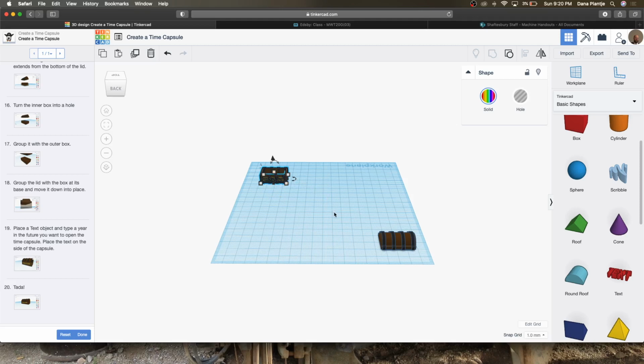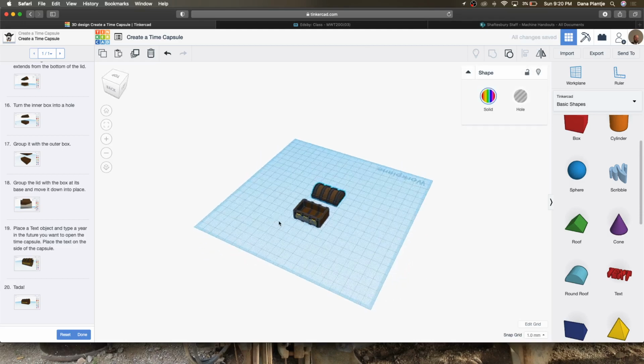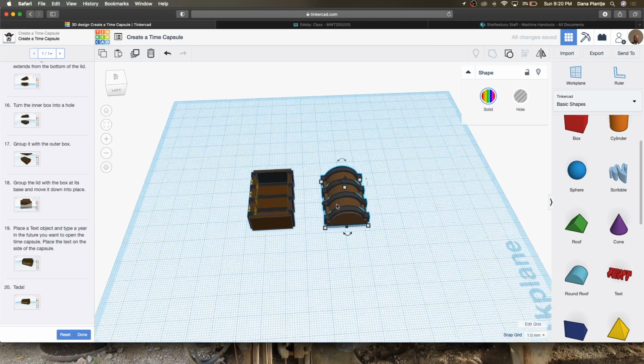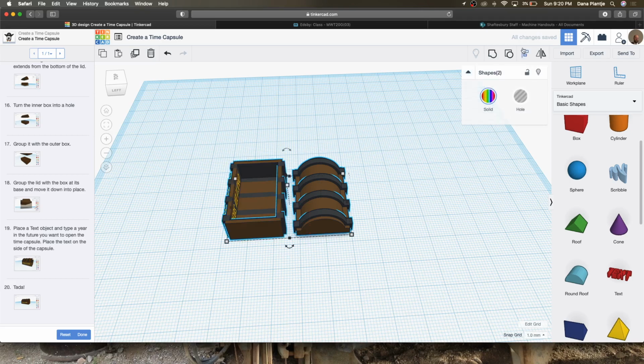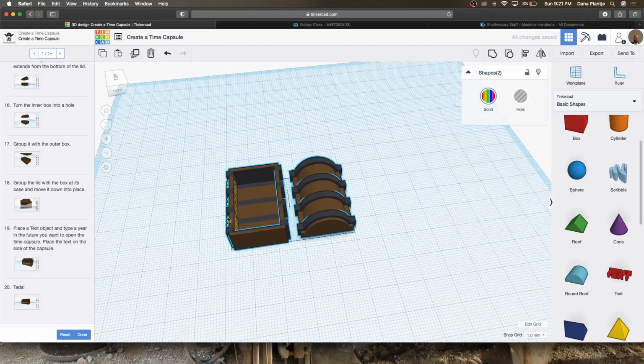That's going to take a lot of time, and you have a limited amount of time for your project to print it in. So in order to speed up the process for you, I would recommend that you move your 2 objects so that they are in fairly close proximity so that the printer doesn't have to move very far. Okay, so they can sit fairly close together. And just to make it, again, a little bit easier on the printer and reduce print time, we'll center them.